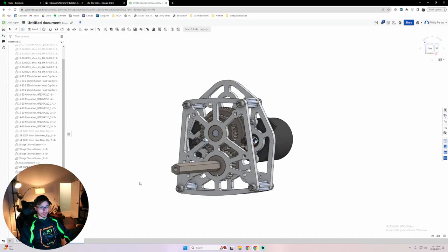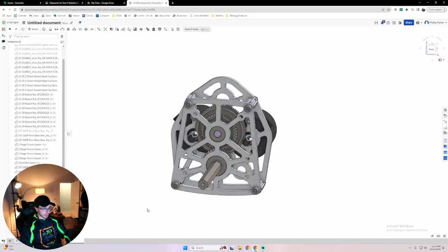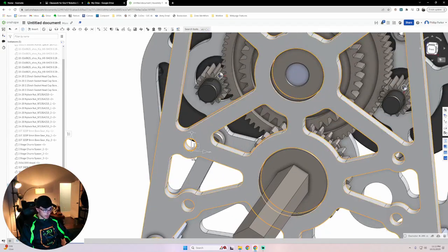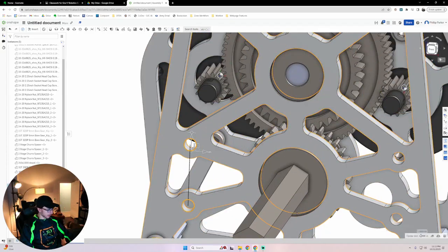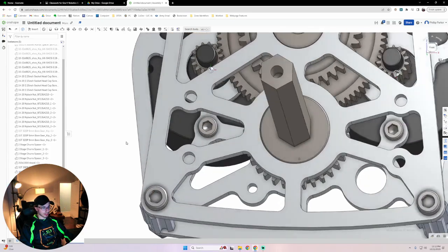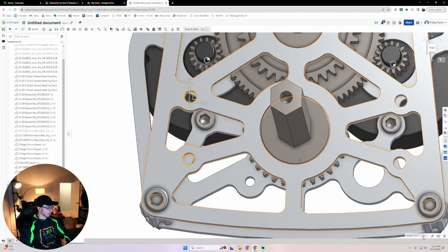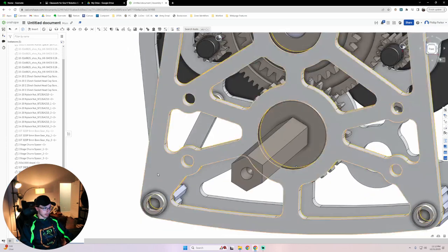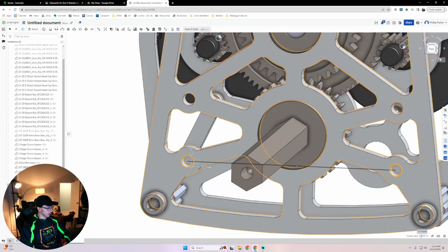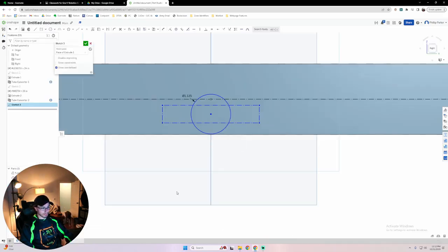now what we're going to do is I'm going to take a look at this. I'm going to measure the distance between here and here. Notice how when I select two objects, it gives me an output in the bottom corner, 1 inch. That's really important because we can reference that later. Okay, same thing. I'm going to take it over here. Oh, it's 3.375. Okay, I can go back to my parts studio.